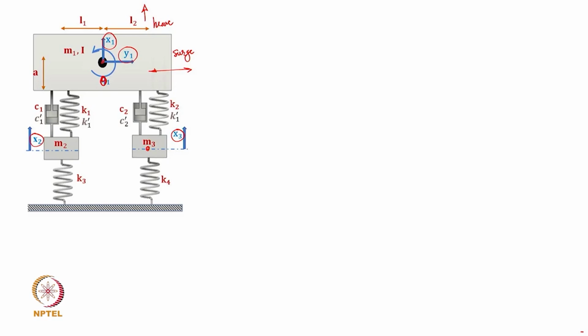Now, what we are also going to make use of are the damping property of the dashpot or the suspension, defined by a damping coefficient C1, and the suspension stiffness K1 in the vertical direction. Similarly, K2 and C2 are the stiffness and damping coefficients of the front suspension. K3 and K4 now quantify the tire stiffness, because the wheel mass is separated from the ground through the compliance of the tire. Based on the tire characteristics and the air pressure, it will have its own stiffness. In general, this stiffness is going to be nonlinear, but for the sake of initial analysis, it will be considered a constant stiffness K4 and K3.